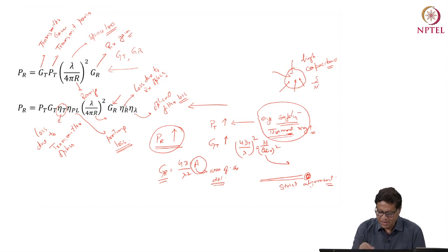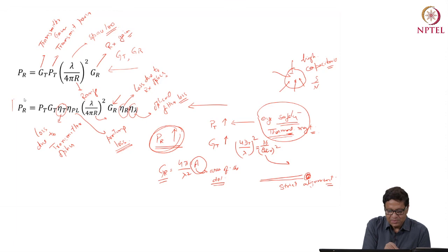And similarly, one has to use optics which has less loss at the receiver. And the same logic is for the filter which you are using, you should have minimum loss. So you see here the trade-off. In order to get high PR, I can play with different components, but every component, or every parameter, has some limit. So this is how it becomes a design problem.